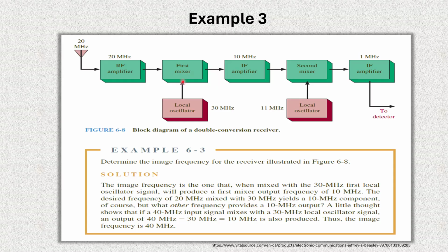40 megahertz. Then later you take it down from that upper frequency, and you go with 11 megahertz minus 10, and that's going to give us 1 megahertz. So all of a sudden, from 10 megahertz, you are translating that into 1 megahertz.